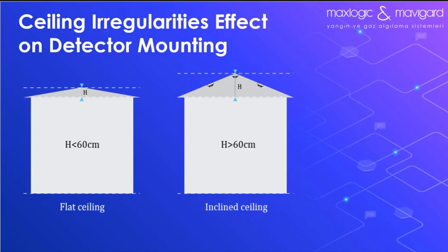After the change, 6.5.1 General, statement B, flat and sloping ceilings: if the protected area has a pitch roof, detectors should be placed at each vertex. If the height difference between the bottom of the sloping ceiling and the top of the roof is less than 60 cm, the roof is treated as flat if smoke detectors are used.